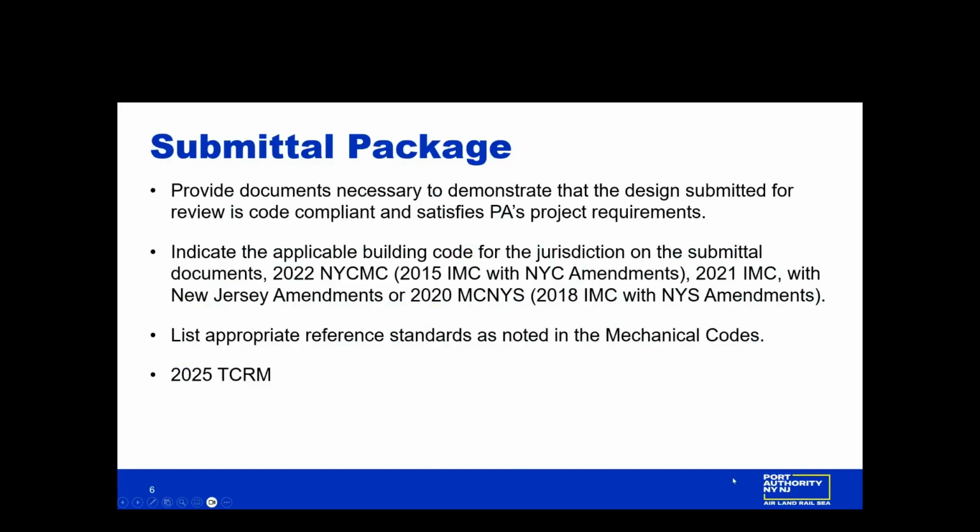Indicate the applicable building code for the jurisdiction on the submittal documents, whether it's New York City, New Jersey, or New York State. We do cover 3 different jurisdictions. List the appropriate reference standards as noted in the mechanical codes. And of course, the 2025 TCRM, the Tenant Construction Review Manual. Next slide, please.